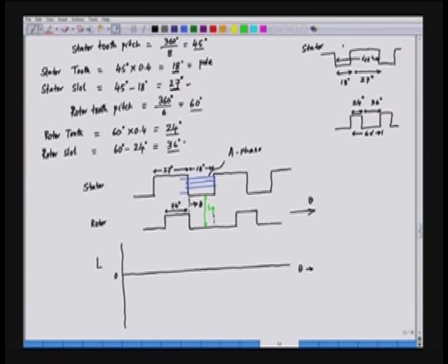So, gradually the rotor will move under the stator. After some time the rotor will go under the stator. So, this will be somewhere here, and this particular portion will go somewhere here, because this is moving to the right side. So, the stator will see a decreased air gap, and the inductance of phase A will gradually increase.